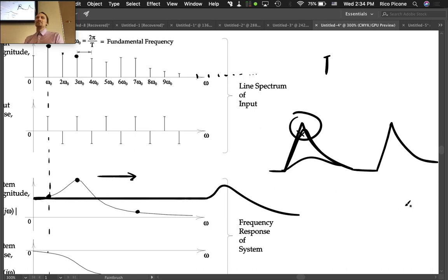So, yeah. Is that kind of down to like the price of the tool? Yeah. So a lot of times it's an economic trade-off where you're like, what do I really need from this measurement? Maybe you want to characterize it to find out, maybe you just want to sense when something goes over it. In which case, maybe just a little bump is fine. But if you want fidelity to what the actual profile looks like, you're going to need to get typically a more expensive sensor. It's not always more expensive, but frequently it is. If you need the dynamic range of your measurement device to go up to those higher frequencies, oftentimes it's more expensive to do so.